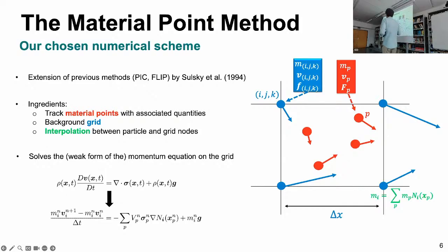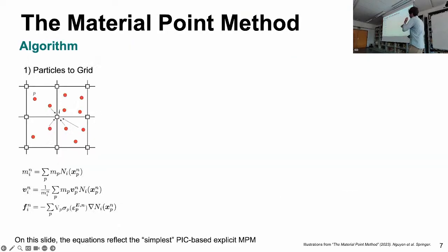So here I show you basically the simple discretization of the momentum equation, here just assuming an explicit time step, and then you have the forces, internal forces from the stresses, and the forces of gravity. So that's conceptually how it works. Let me go a little bit more into the details of the algorithmic steps.